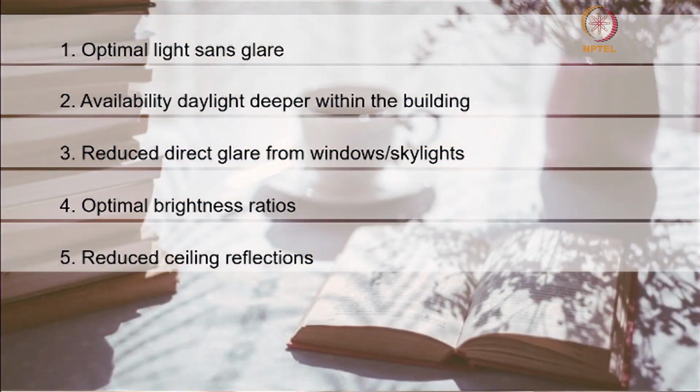It's also to prevent the ceiling reflection, which is created by overhead openings. So, very often when you have skylights, you will get a situation where there is a shadow over a book, or you get your reflection off of the ceiling into the task or into your desktop, which can create discomfort, visual discomfort.